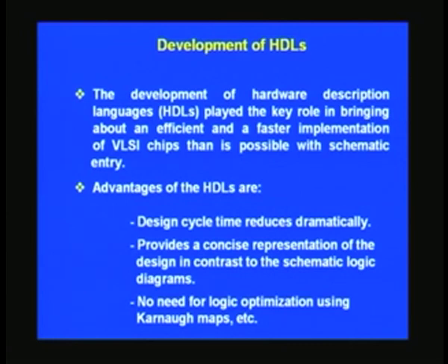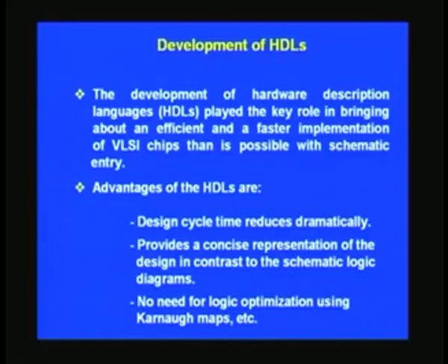There are what are called behavioral statements and RTL statements, and all this can lead to very concise description of the digital hardware that you are designing. In contrast to this, in schematic you have to really put gate by gate, and it will take quite an effort to achieve the same end result. And there is no need for K-map and Quine-McCluskey way of reduction, because the synthesis tool is supposed to take up this role.